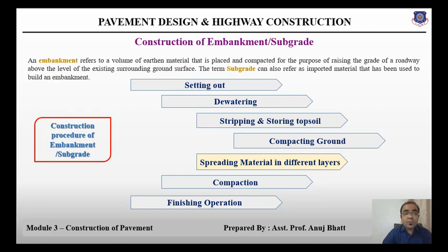If the material delivered to the roadbed is too wet, it shall be dried by aeration and exposure to the sun till the moisture content is acceptable for compaction.